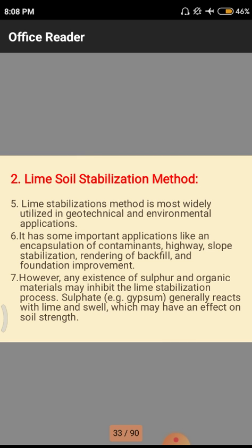Why? Because if there are any disadvantageous materials, automatically those materials will form a bond with calcium, and that calcium will be in an unreacted state, and in that state adding calcium is also not suitable for strengthening properties. So while we are going for this kind of technique, we have to do a chemical analysis of our surrounding soils.